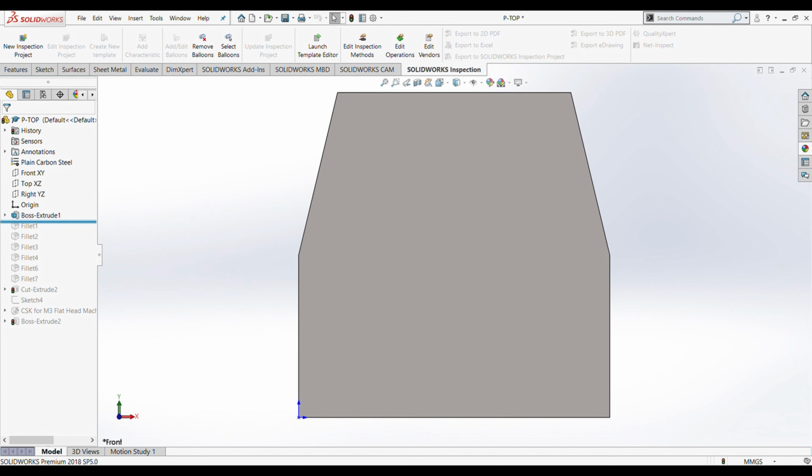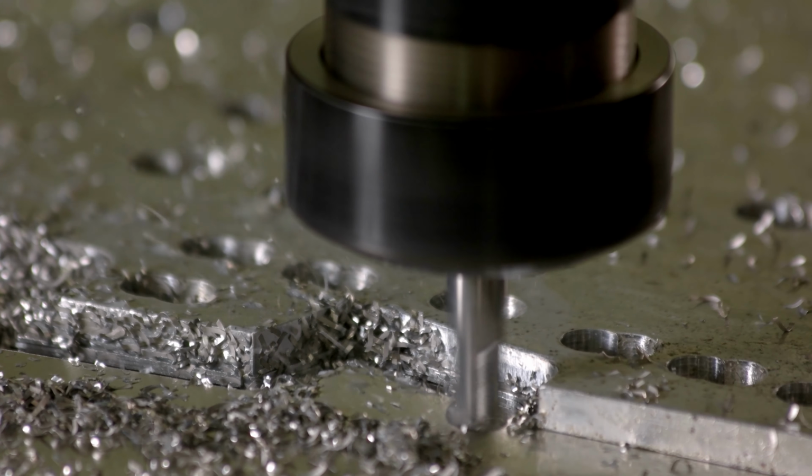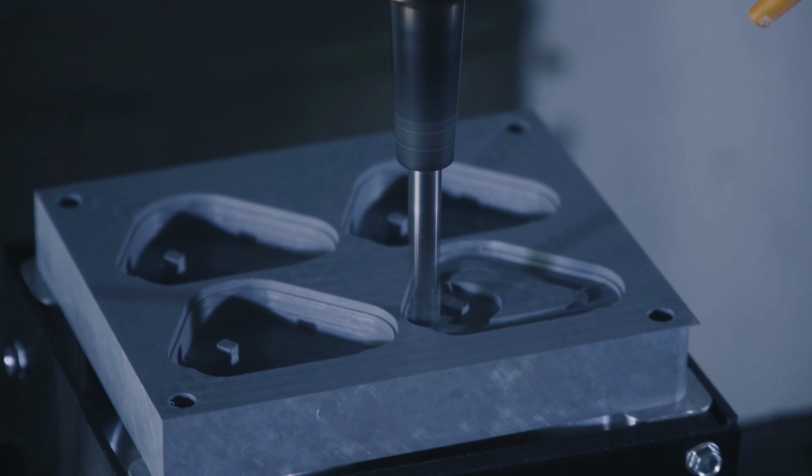In order to fix this, we can use fillets and radii, so incorporate rounded edges wherever possible. For example, instead of a 90-degree internal corner, use a corner with a radius of 1 to 2 mm to reduce the stress concentration and ease manufacturing. Don't forget that the minimum radius also varies depending on the material and depth of the feature, so plan accordingly.